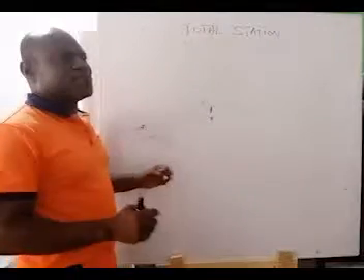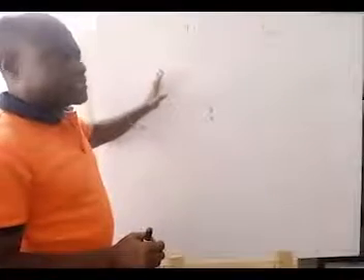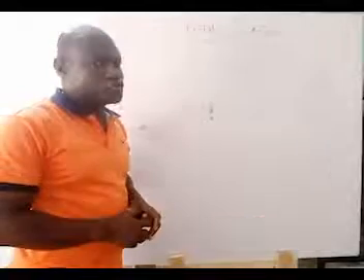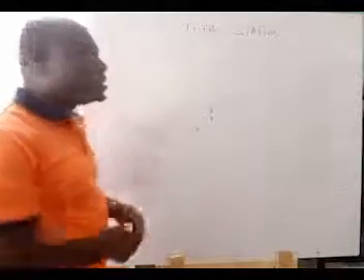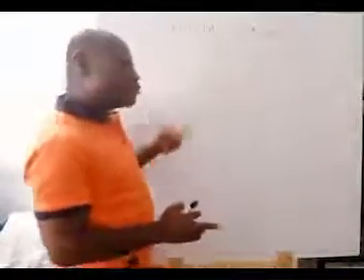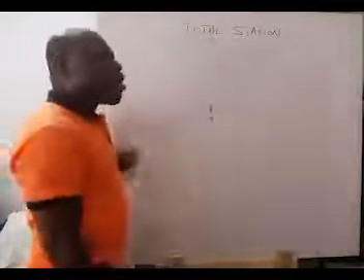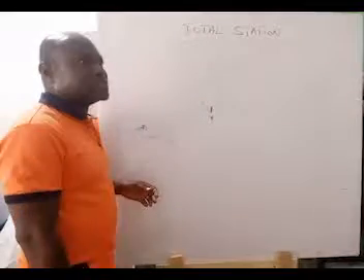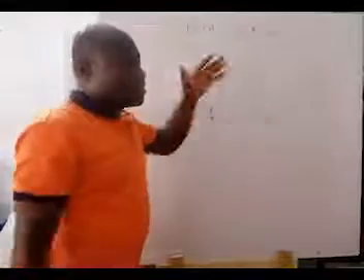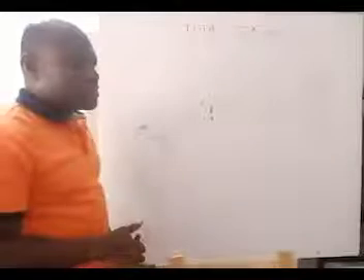And one thing that I want to talk about is the line function in the total station. The line function is very useful for construction, because mostly in construction, all lines are either parallel or perpendicular, and the line function will help you do that. If you take a building, for instance, every wall is parallel to another wall or perpendicular to another wall. So it helps you to set out all the walls, all the components. If it's height, it can even help you, maybe lintel height and all that. So that's what the total station does.